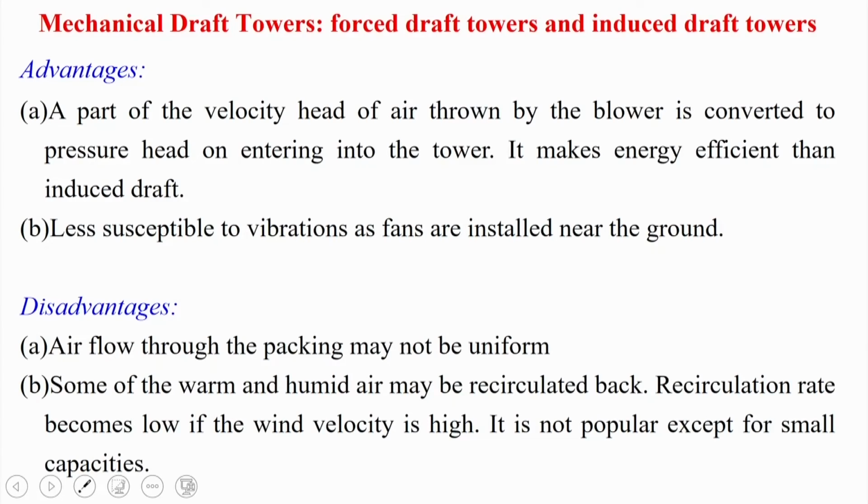The advantages of the forced draft cooling tower are like this: a part of the velocity head of air thrown by the blower is converted to pressure head, because the air blower is used on entering the tower. It makes it more energy efficient than the induced draft, as the air enters with more pressure head, moving at very high speed.